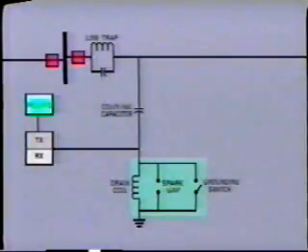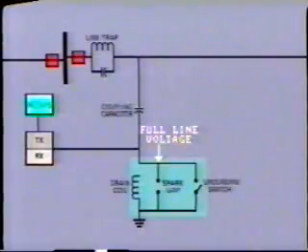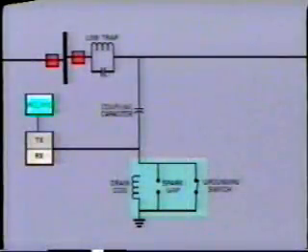If the drain coil were to fail and become open-circuited, it would open the ground on the coupling capacitor. Full line voltage now appears on the protective gap. This fires and an arcing sound is produced indicating an open drain coil. At this point, the maintenance staff will have to hot stick the grounding switch closed and replace the drain coil and perhaps the gap.